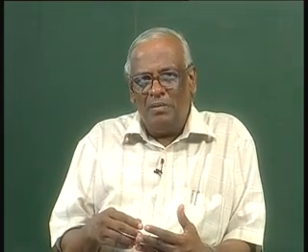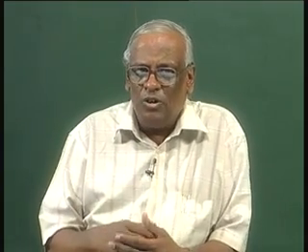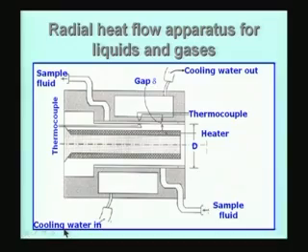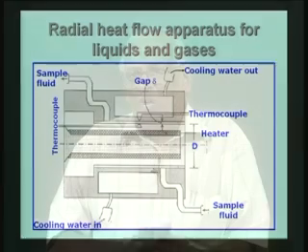If you remember, in the very first slide I said the losses can be reduced or eliminated or estimated and accounted for. So, in the present case what I have to do is to find out what the loss is, and let us look at how I am going to do that. Suppose I take either a liquid or a gas of known thermal conductivity in this gap. The easiest thing is to take air, you do not have to do anything, air is everywhere, you just allow the entire gap to be filled with air.